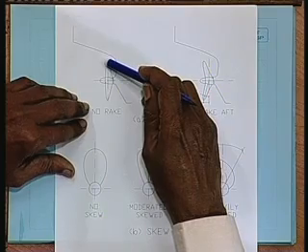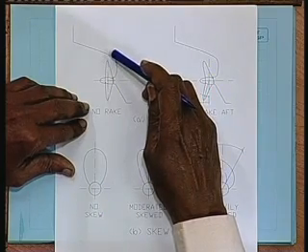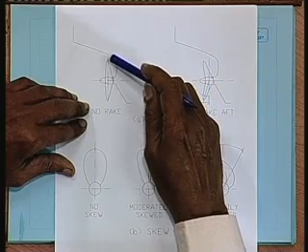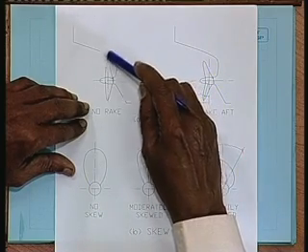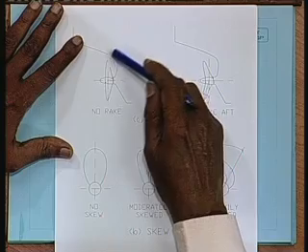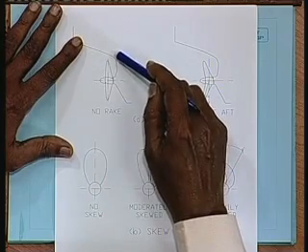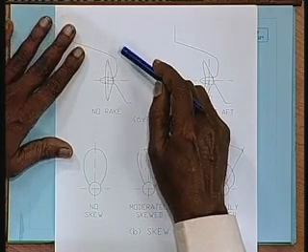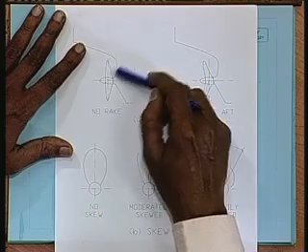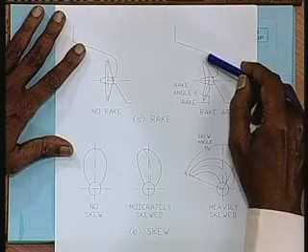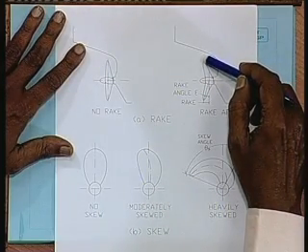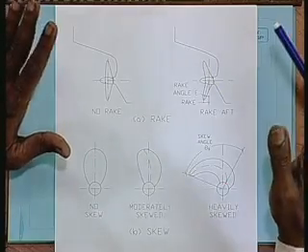One way to reduce the effects of this vibration is to increase the clearance between the propeller tip and the hull. This minimum distance, as I have discussed earlier, is given by classification societies. So, if you do not get adequate clearance here, raking the propeller is one way so that we can increase the clearance between the hull and the propeller. Okay.